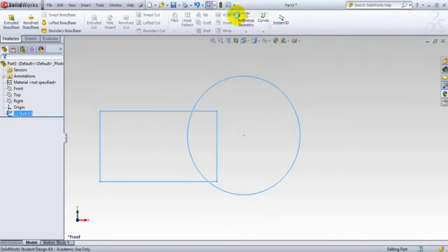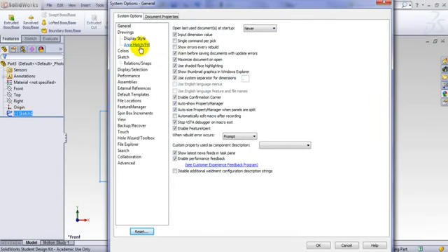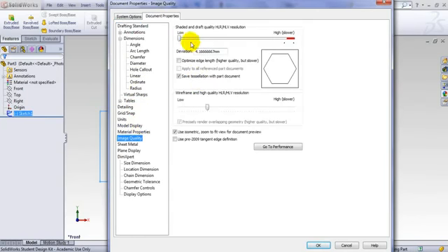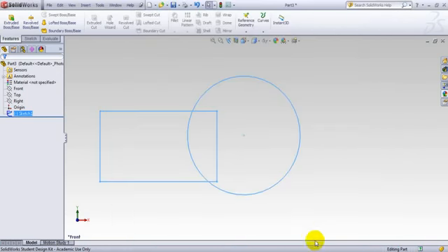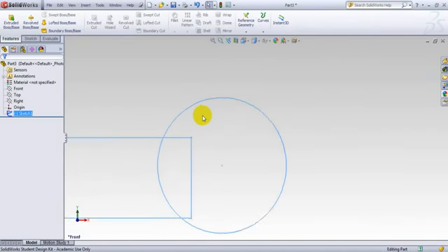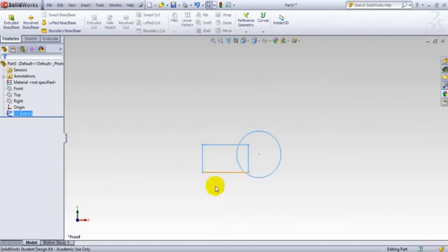If I want to change the resolution, I go here, and again it depends on the size of it. If it's very small, it would be completely pronounced. So I go to properties, and I go to image quality, and usually I put it in the middle. As you can see, it's about 0.25. That should be sufficient, and it is okay. And you can see now it looks much better and has a much higher resolution. It's not the broken lines connected to each other.